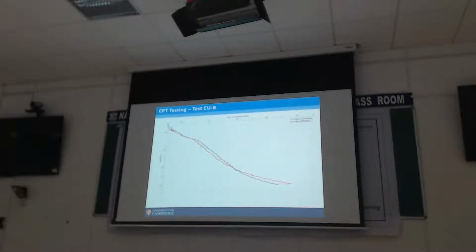Now, you can see it's quite consistent increase with depth. There is a little bit of unevenness for various reasons of model making, where you stop to put the instrument. When you start it again, the machine may pour a little bit of a loose layer or something like that. But we know what it is and where it is. That's the good thing of doing in-flight simulation.